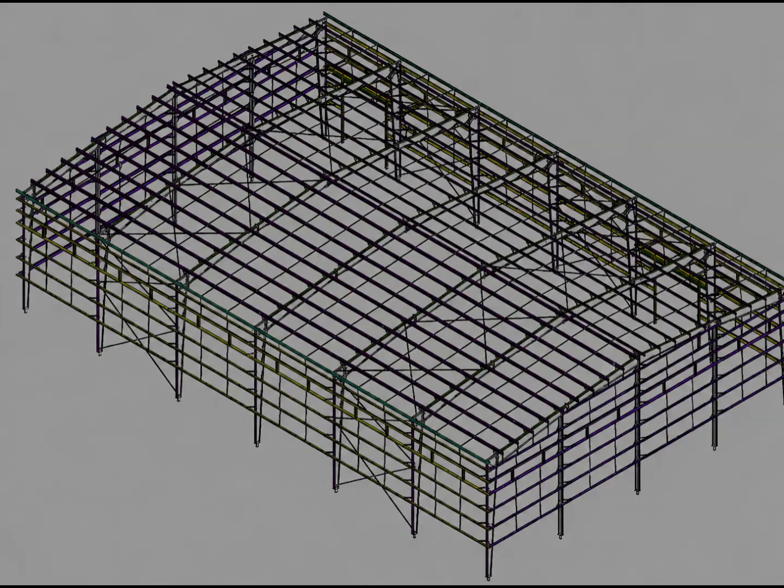You can also see diagonal members in the roof framing. These are visually much more obvious because they form diagonal patterns across the roof bays. That is different from the sag rod arrangement we have been studying. The roof X-bracing creates a clearly visible diagonal pattern. The sag rod arrangement is comparatively subtle. So, when looking at a complete 3D model, it is very easy to notice the X-bracing first and completely overlook the smaller rod members. This is exactly why close inspection is necessary.